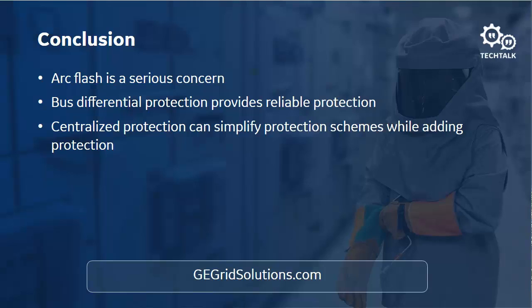The loop sensors, that's the point sensors. For the loop sensors, when they're running them through the switchgear, I've seen where they get crimped down too tight, they can crack, and then you don't get the protection you're looking for. So they're not as robust as something like the bus protection, which is using CTs, which are very robust, or the zone interlock scheme, which again is using the CTs. There is some communication involved with it, but it uses GOOSE messaging, so you get a lot of speed out of this.